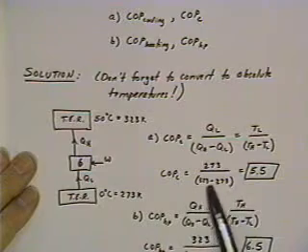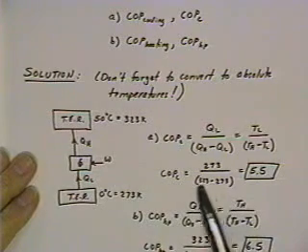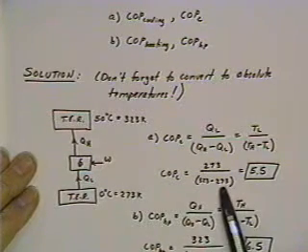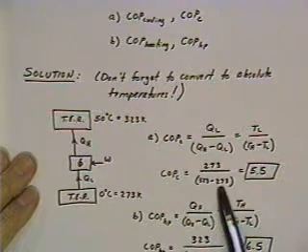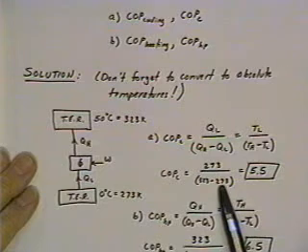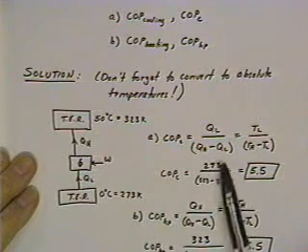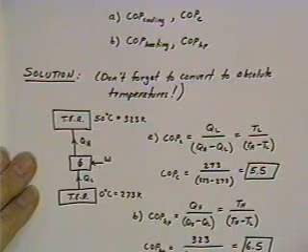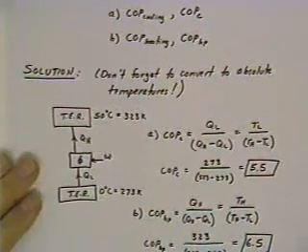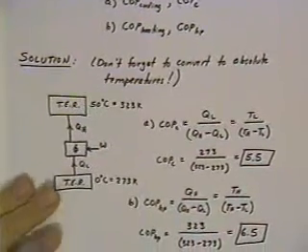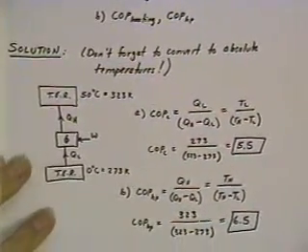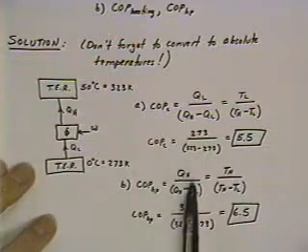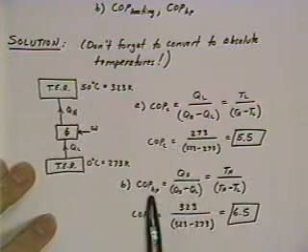Again, you would not have to convert these to absolute temperatures for the difference, because when you're talking about temperature difference, Kelvin and centigrade are of course exactly the same. However, if you didn't convert the 273 to absolute temperatures, you'd end up with a 0 on top, and you'd get a COP of 0, of course, and that would be the wrong answer. So you get a COP for cooling of 5.5. For heating, you get your COP for a heat pump.